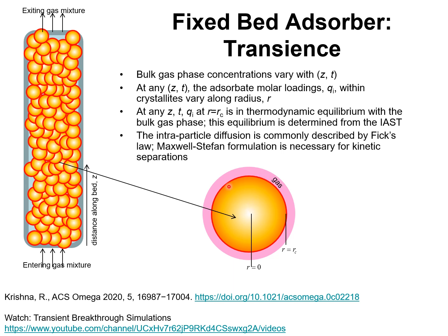The description of the uptake of the components within the particle forms a small part of the computational load to determine the transient development of concentration profiles within the fixed bed and the determination of the breakthroughs that are important to describe mixture separations. Such breakthroughs are of vital importance in the design of fixed bed adsorbers.